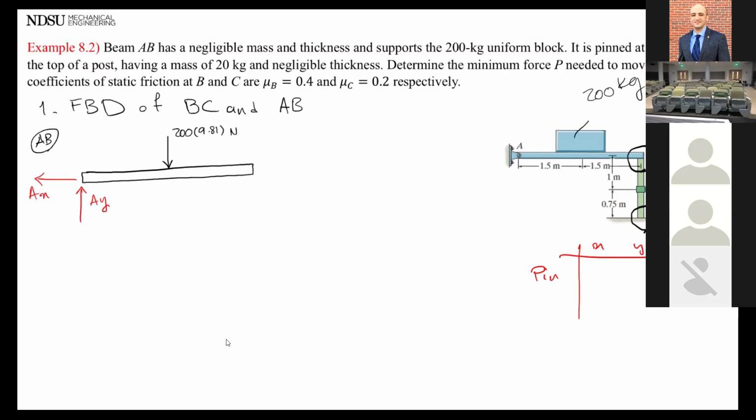And because it stops it, it generates forces. Or because it generates forces in that direction, it stops it. Okay, so in X, can it move? No. In Y, can it move? No. Can it rotate about point A? Yes. And remember, we only said these are going to generate reactions. So that's why it doesn't have a moment. Okay, so a pin never has a moment as a reaction.